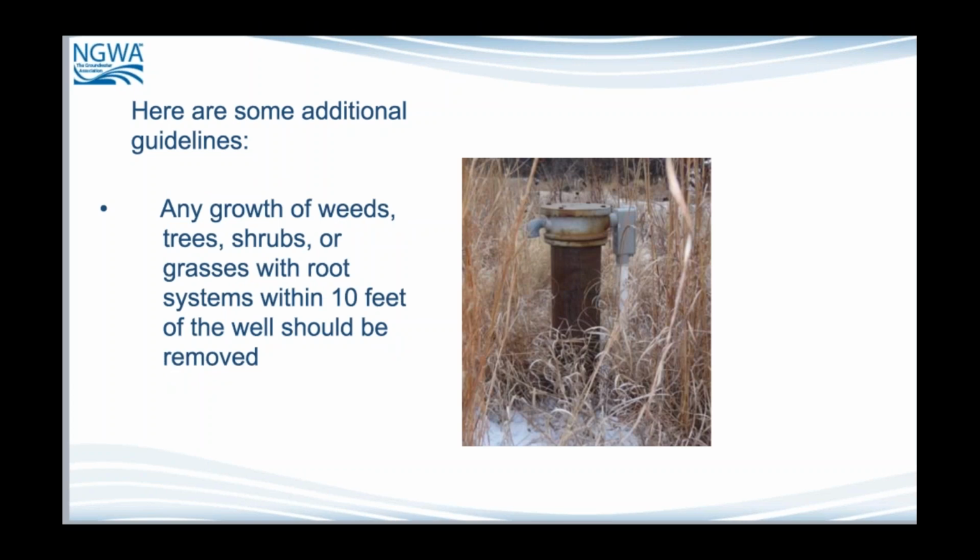With the growth of shrubs and things like that, you want to make sure that you can find your well and see what's happened to it. As you're going around mowing or taking care of it, make sure your cap's still on and that the conduit for the wire has not been broken. If somebody comes through with a lawnmower and knocks any of that off, then it can get contamination through insects, rodents and mice.